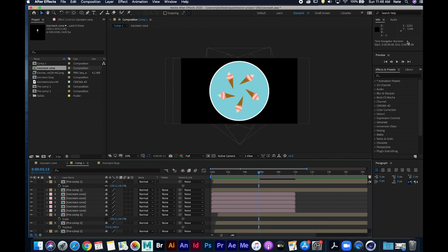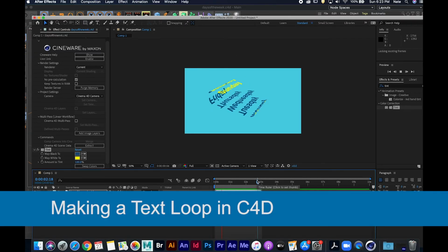And it doesn't quite render it full, but once we go back and once we have the area that is rendered, we get the real-time render. So that's how you, if you have really complicated movement, maybe more complicated than what we have here, then you could bake your footage into an image sequence and use that instead of the Cinema4D file.